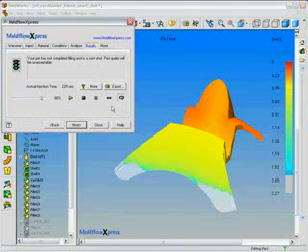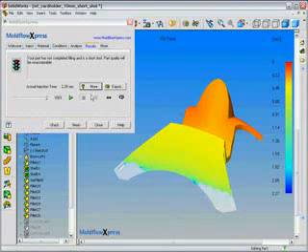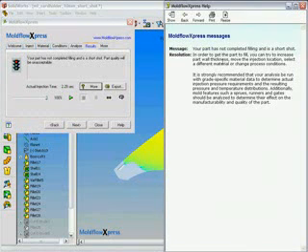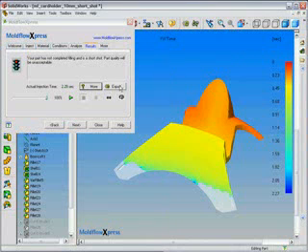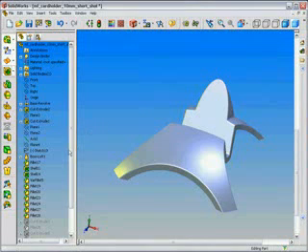We can step through the time plot, and what we see is that the bottom feet of our business card holder are not going to fill. This is what we call a short shot. Now we can click on the information button to find out what types of things we could change. We could change the material, we could change the wall thickness, or change where the part is filled. Results from MoldFlowXpress can also be exported to an eDrawing.